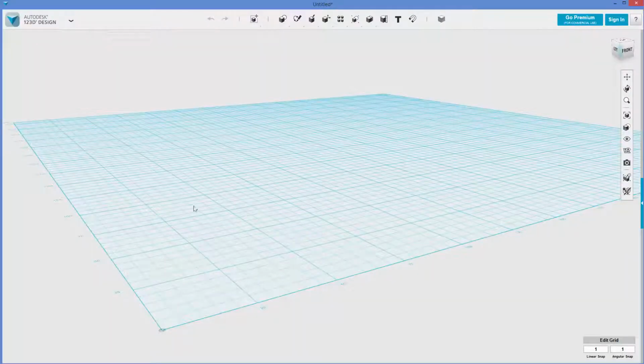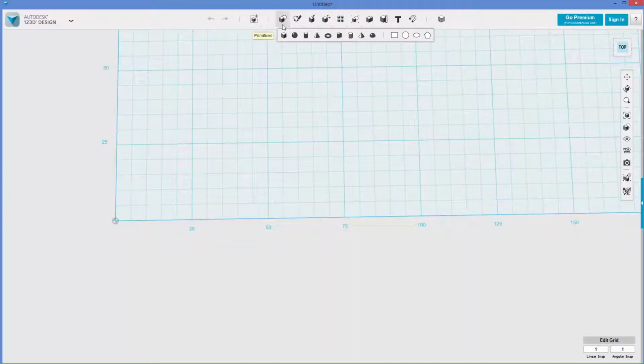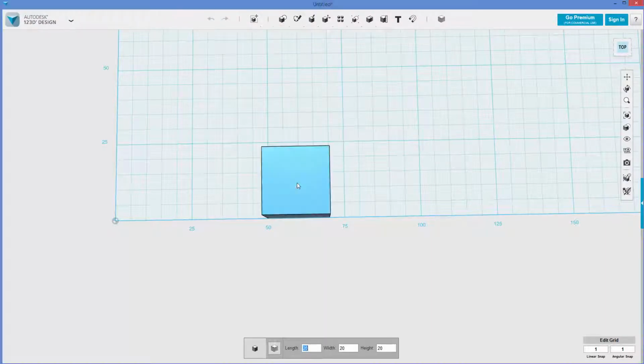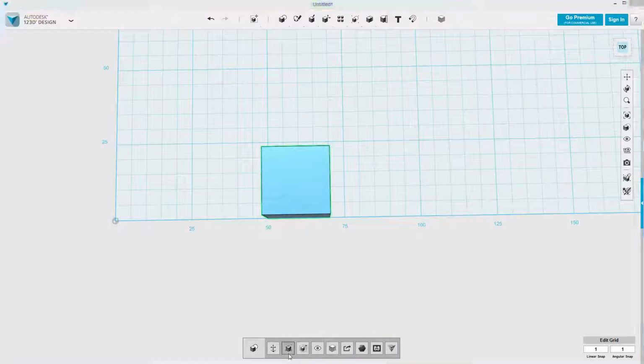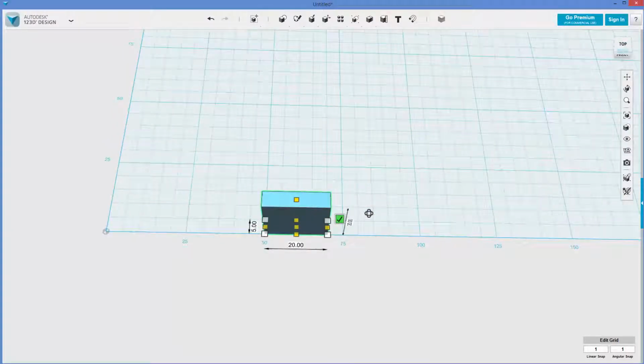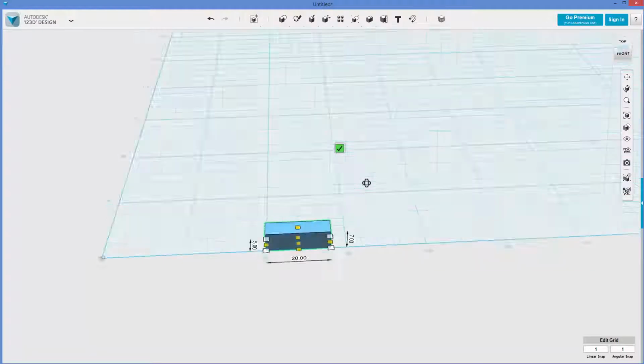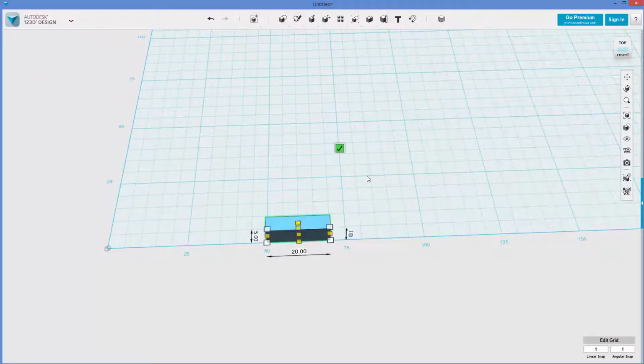So I'm going to start creating some feet for the lander. I'm going to get a view up like this, drop a block on, and smart scale this. See how I can click on the model, see how it highlights when I mouse over, and then when I click on it, I now have these options. I'm going to click smart scale and drag this down until it's kind of flat like that, and make this a little shorter this way too. So that looks about good.